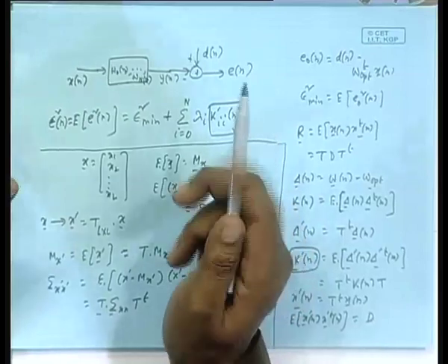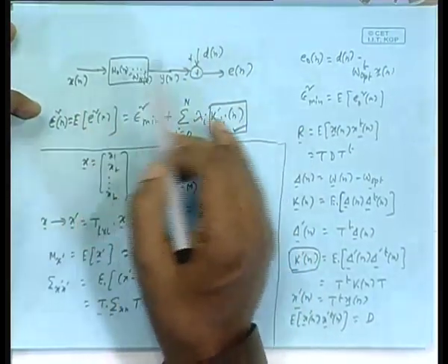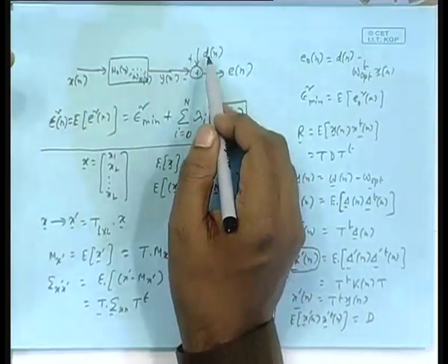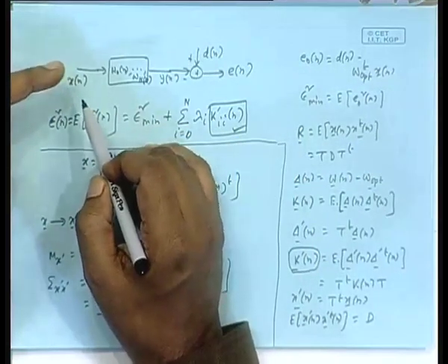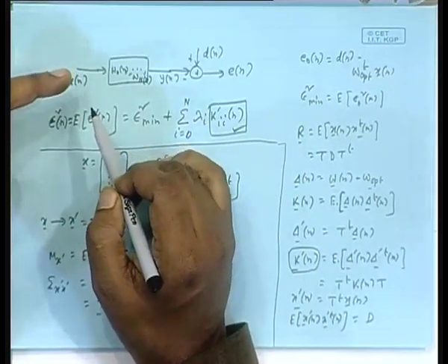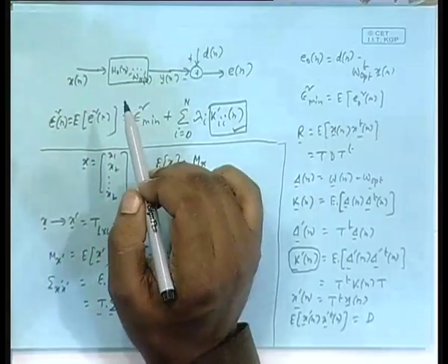We will make the assumption that the joint density between Dn and the components of the Xn vector, that is Xn, Xn minus 1, Xn minus 2, up to Xn minus capital N plus 1, is a jointly Gaussian vector. The vector consists of variables which are jointly Gaussian. This is an extra assumption, and a fine one, because Gaussian assumptions usually work in practice.